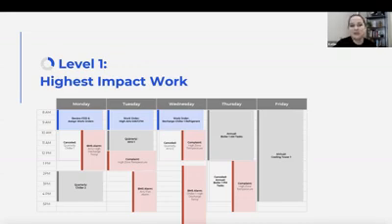So let's look at one example where you might be able to use FDD to supplement some of your PM work and to help you get your feet under you with maintaining your facilities. Let's just do highest impact work. So these blue squares would be where you'd be doing something that's FDD related. So maybe on Monday morning, you come in and you look at your FDD software and you assign some work orders. So you're planning your FDD response work. You're not stopping what you're doing and going and responding to a fault. You're planning it and you're scheduling it.